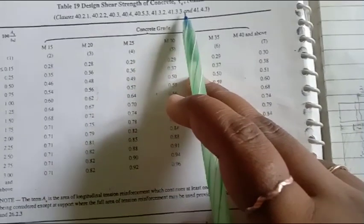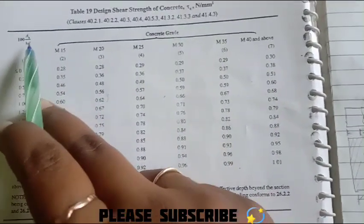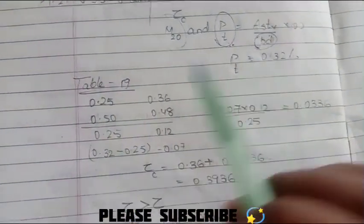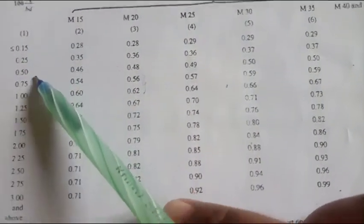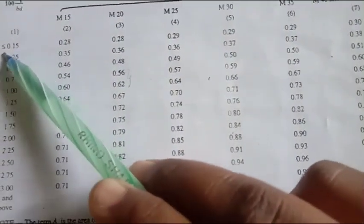Here, see, this is the table which I was talking about. The design shear strength, tau c, depends upon the pt, that is the percentage of steel provided, Ast by bd into 100. So here we have got the pt value as 0.32%. We just have to find which values 0.32 lies between. Over here we can see Ast by bd into 100 values of 0.15, 0.25, 0.5, 0.75. We got the value of 0.32, that is in between 0.25 and 0.5.